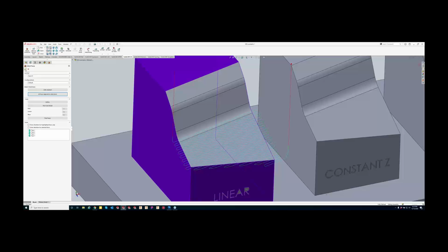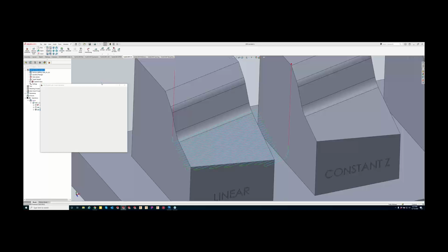And the nice thing about that is now I can tell it that, instead of doing a retract, to trim and relink the tool when it hits that surface, and I can also put a tolerance and or a stock to leave in there. So maybe if it's hitting right here and I have a 45-degree surface, to leave 5 thou in there for a different tool path to come in there.